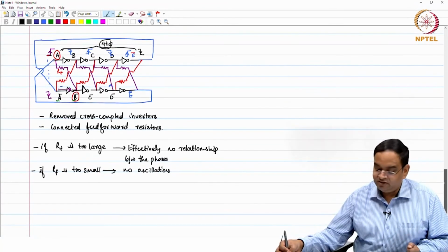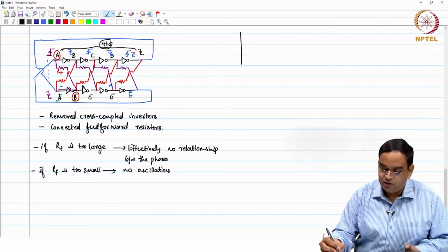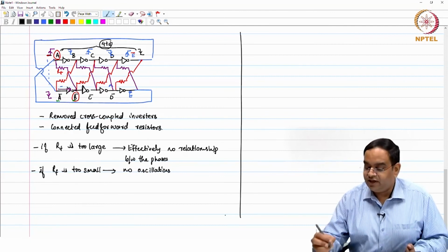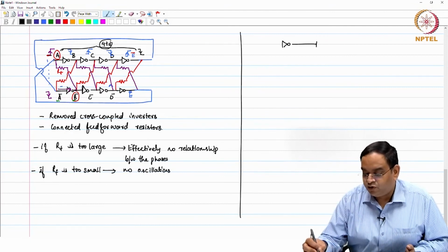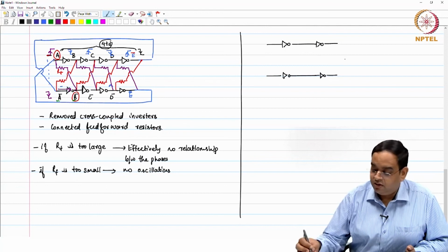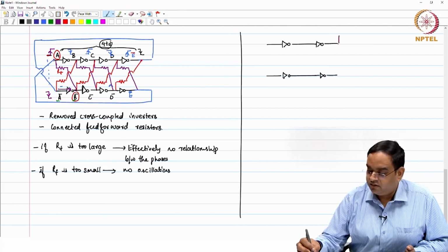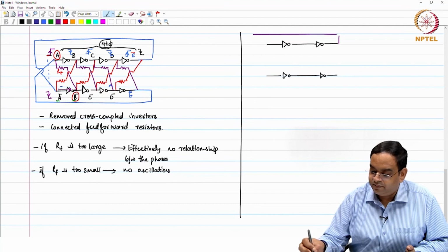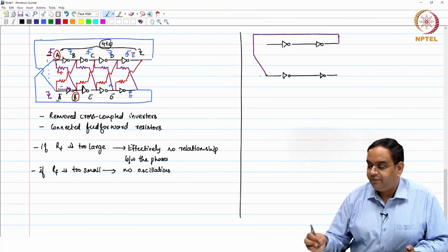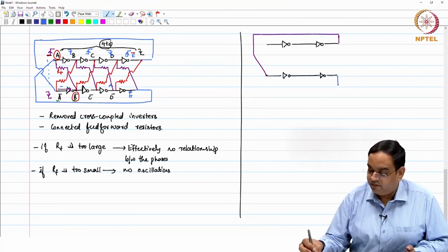One interesting thing here is that the one which we have used is using 4 or 8 inverters in the ring, you can say, but if I try to use only 2 inverters like this, where I want 90-degree phase only, right. So, the circuit says that I can very well connect the circuit like this. Okay. And similarly, I can have connection like this.